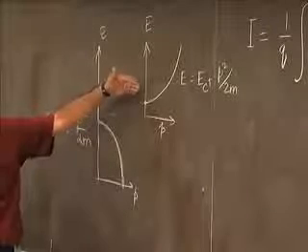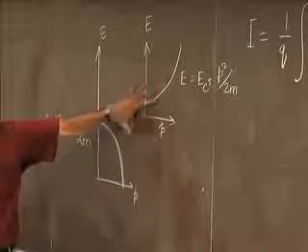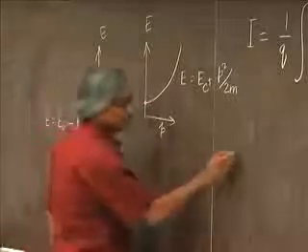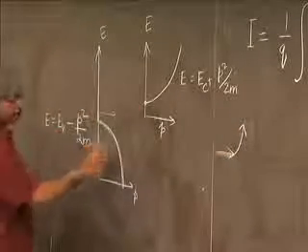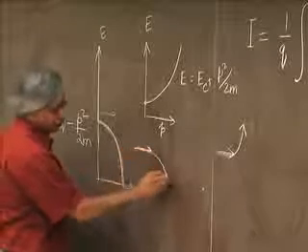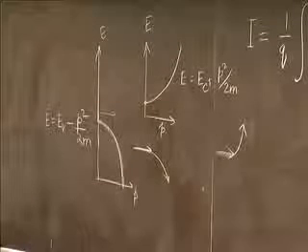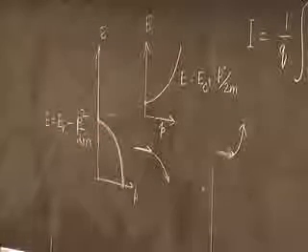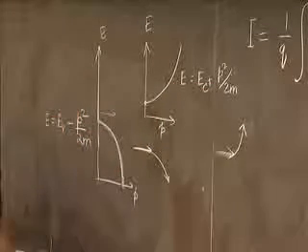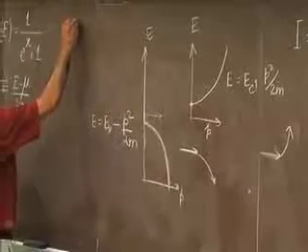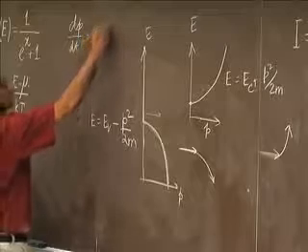The difference between N-type and P-type comes about because when it looks like this and you put a magnetic field, let's say an electron going this way curves upwards. In a material like this, an electron going this way will actually curve downwards. So it's not an F1 minus F2 issue, it's a different thing. And that is again only because of this plus and this minus sign here. Because as I mentioned before, the way you think about it is dP/dt equals Q V cross B.